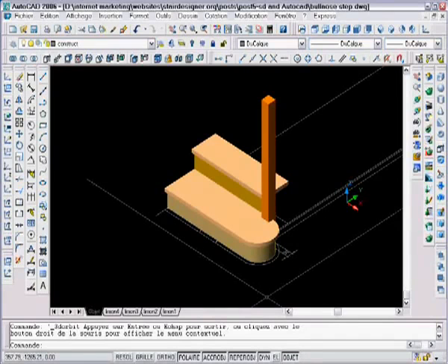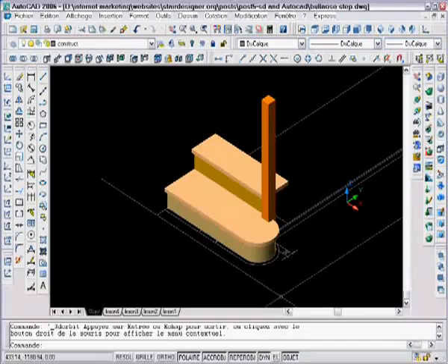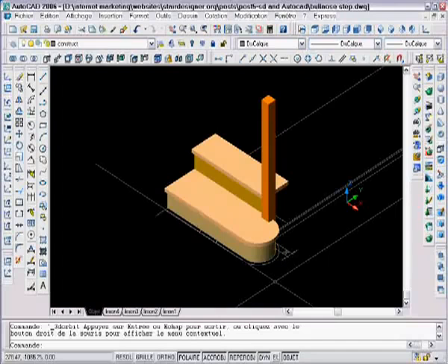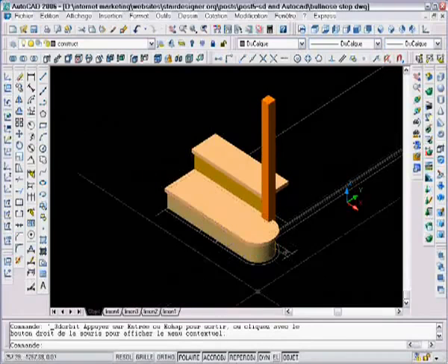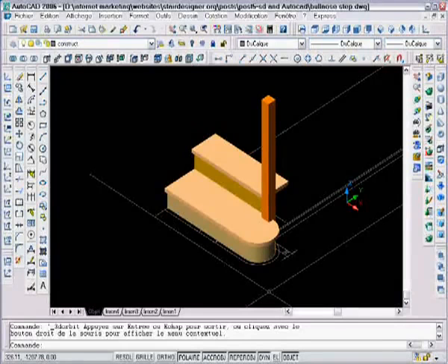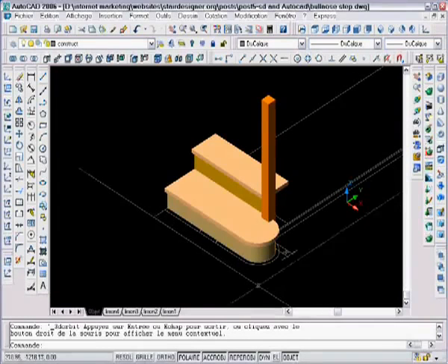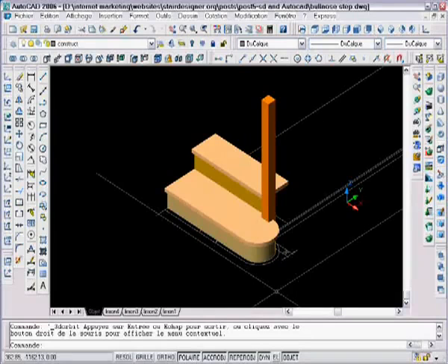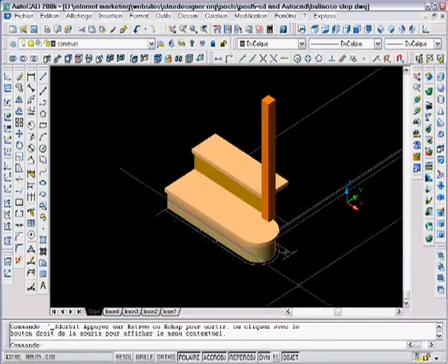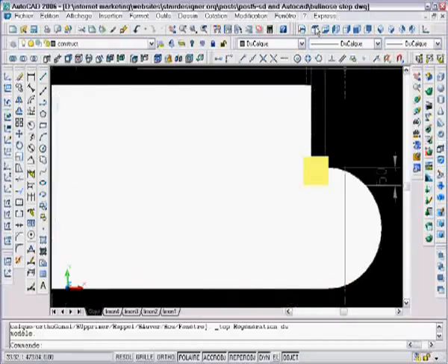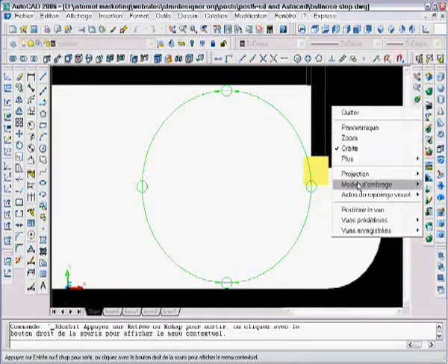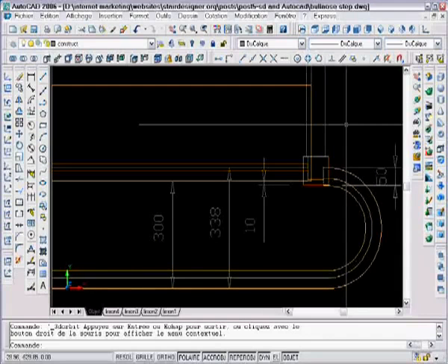It is very difficult to make Stairdesigner respect these different proportions for the bullnose step, because Stairdesigner doesn't draw curved risers. Although I can put a curved bullnose step into the program, as it does parametric curved steps, the risers do not follow. So what I usually do is build the riser very quickly in AutoCAD like this, then I go into Stairdesigner and build the staircase, put the staircase back into AutoCAD, and add the steps. So here's how I do it.